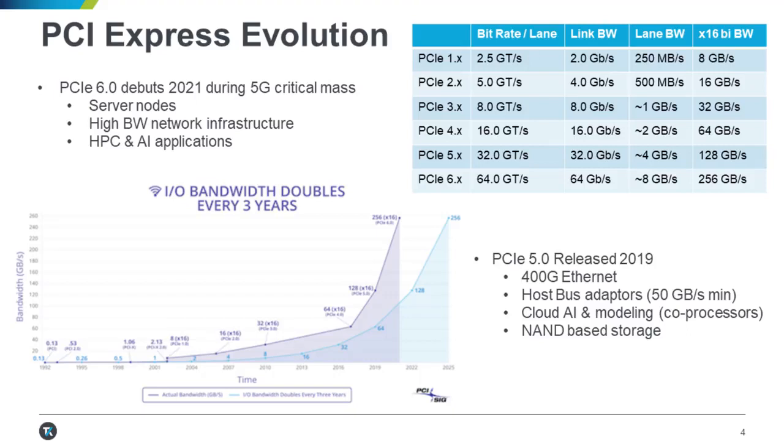And then you can see the link bandwidth, right? And this then takes into account bits that are lost due to, let's say, 8B/10B encoding for Gen 1 and Gen 2. We've moved to 128/130 for the higher rates, and we're at 1B/1B encoding for Gen 6. Next column, we've got lane bandwidth, right?